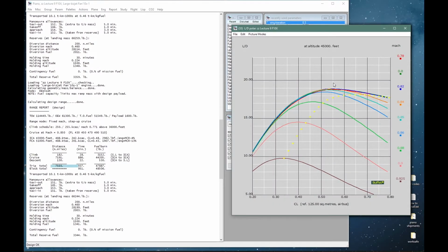It is worth emphasizing that although aerodynamics and performance predictions at normal cruise conditions tend to be very good, at the maximum Mach numbers, near MMO, the uncertainties are always much greater. The manufacturer will have some better indications of the shape of the drag polar at these conditions through detailed three-dimensional computational fluid dynamics. But even with CFD, uncertainties in the drag levels near MMO will still remain high until flight testing gives a better picture.